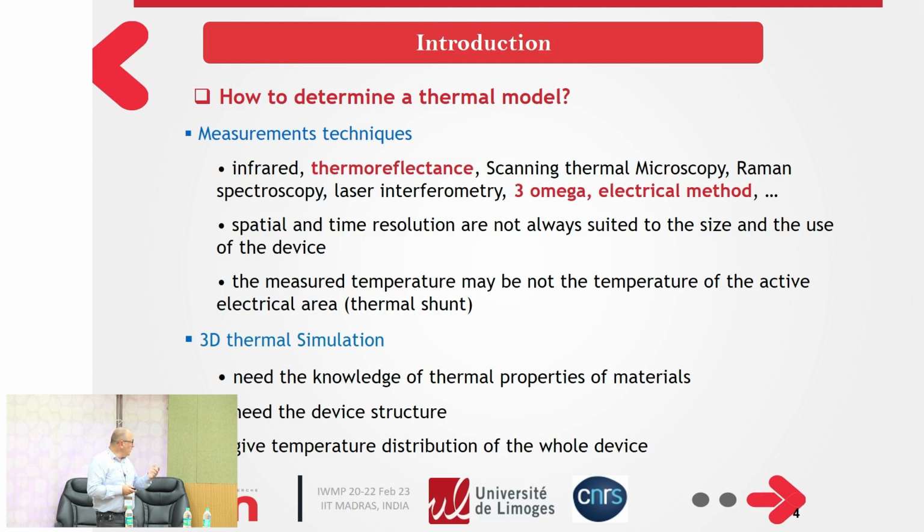And you need the structure of the device, so you need to sign an NDA with the company to have the structure and to simulate the device. Moreover, it gives the temperature on all the structure, so what temperature do you take afterwards? A mean temperature, a peak temperature? This is important in order to have an equivalent temperature for the device.